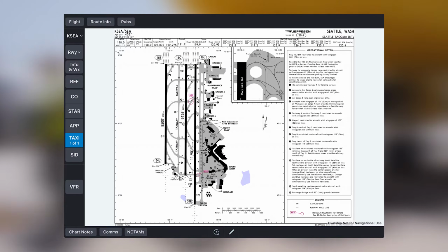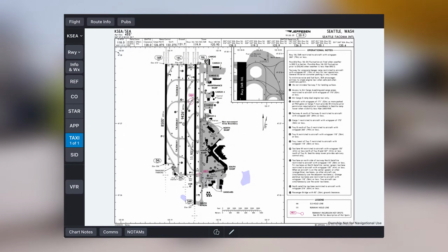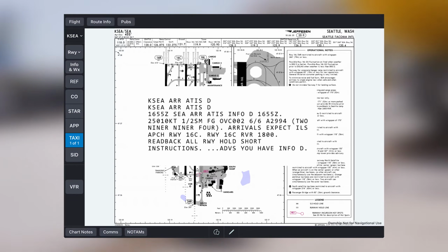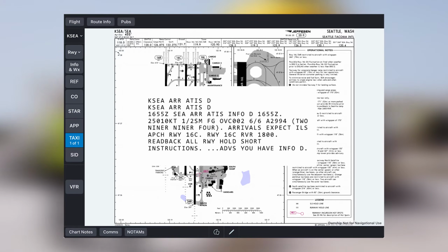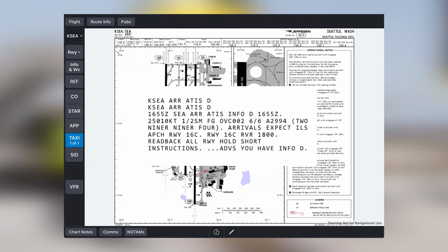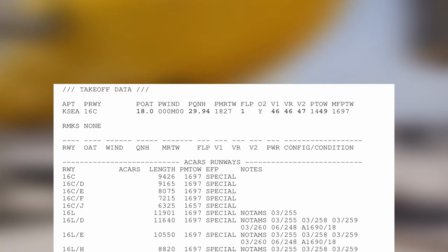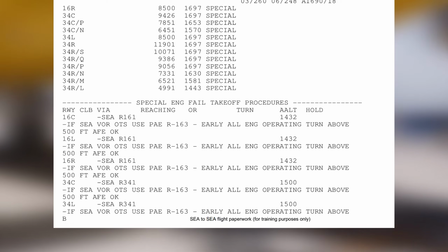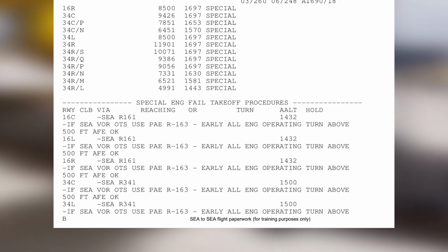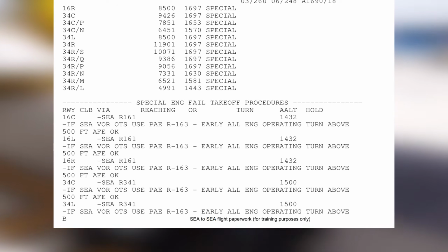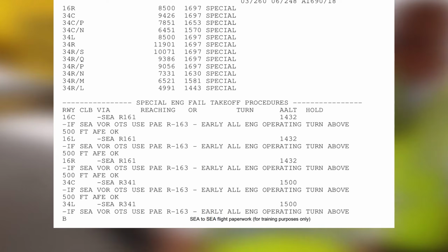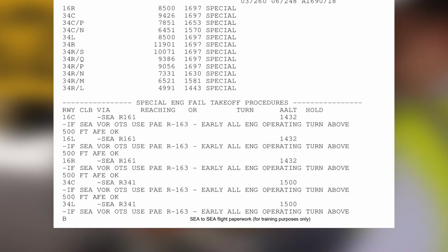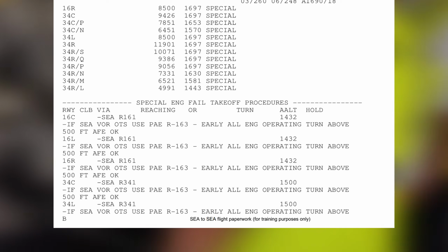Today we are departing from Seattle-Tacoma International Airport, runway 16 center. Current visibility on departure is 1800 RVR, as opposed to our traditional validation scenario of 500 RVR. This means that Neil and John briefed the single engine procedure and plan for a return back to Seattle in case of an emergency. Remember that if weather conditions at the airport of departure are below landing minimums for that airport, Cat 1 being the lowest, you'd build the secondary flight plan to your departure alternate as required by SOP.